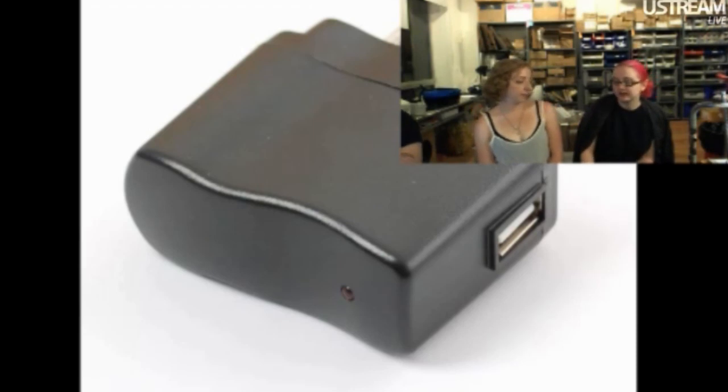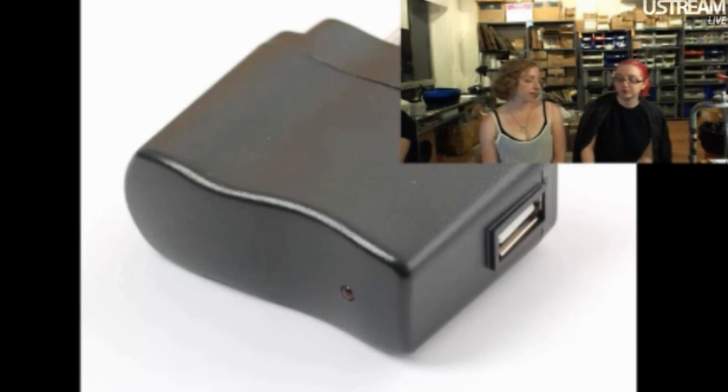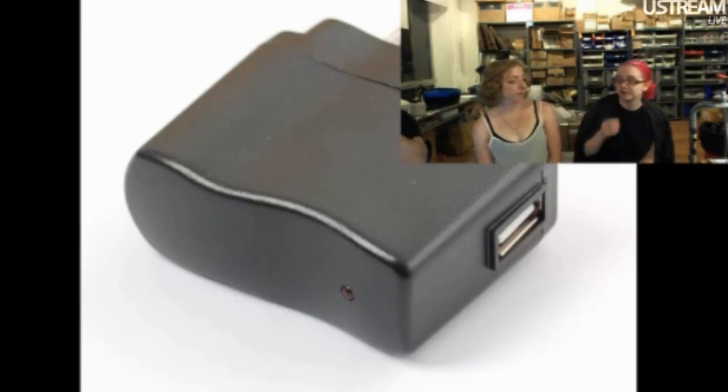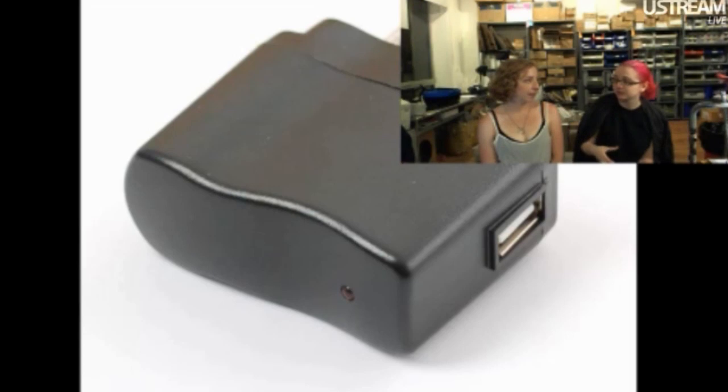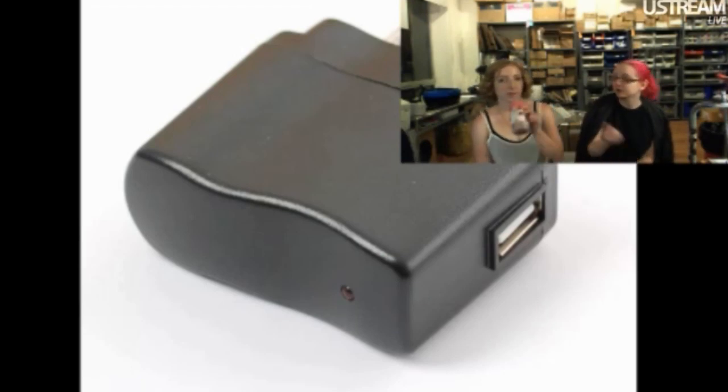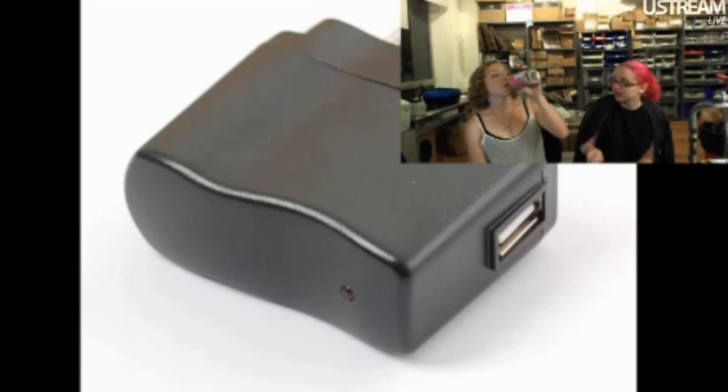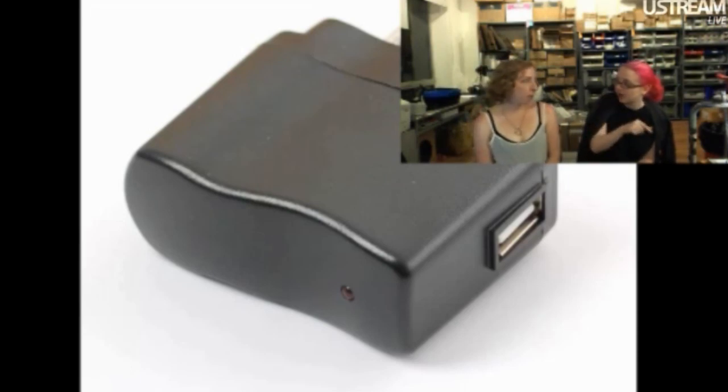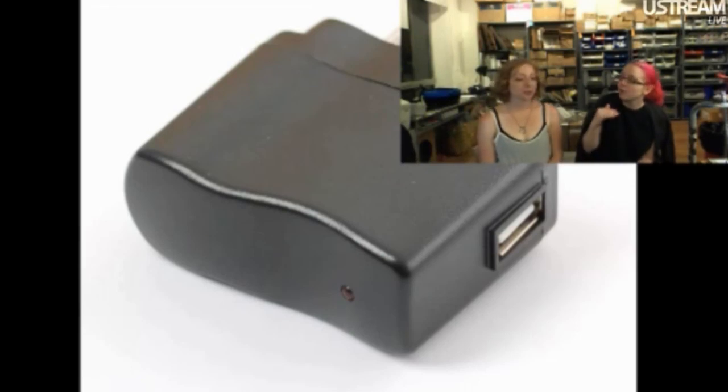All around great travel, and it's got 5.25 volt output, which is really great because for a lot of these adapters, they give like 4.9 volts or 4.8 volts output, which is good enough to charge batteries off of, but not good enough to run something directly off of it. So, for example, if you want to run your Raspberry Pi, which comes with a USB, you can power it with a USB cable. There's a little bit of protection circuitry, and there's a voltage drop, and the voltage drop can make USB accessories not work because they want 5 volts.